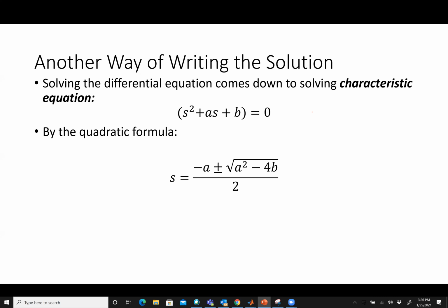And they then define this, and this is commonly used. They define this term called alpha, which is A over 2. And they say that B should be equal to omega naught squared. Now, alpha doesn't have any particularly useful name to it, but omega naught does. Omega naught is sometimes called the undamped, or sometimes called the resonant frequency. So you guys have probably heard the term resonance before. Second order systems can resonate, meaning that they can basically have that kind of sinusoidal variation.